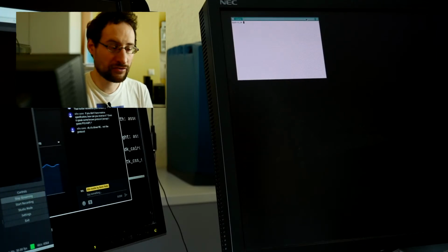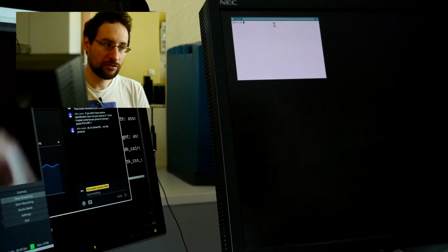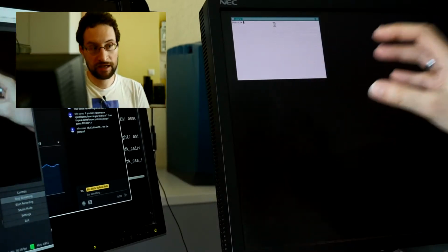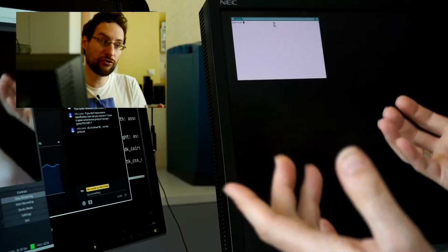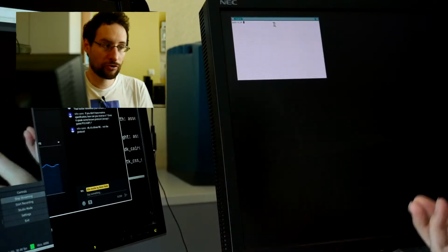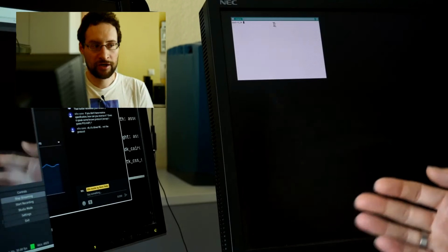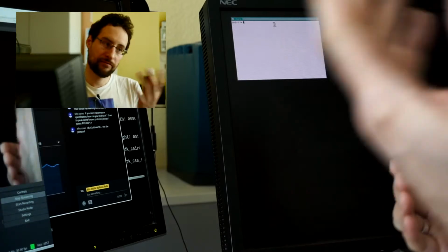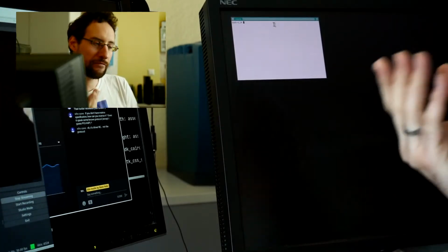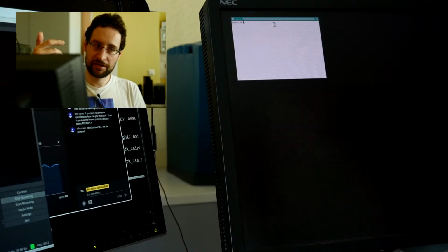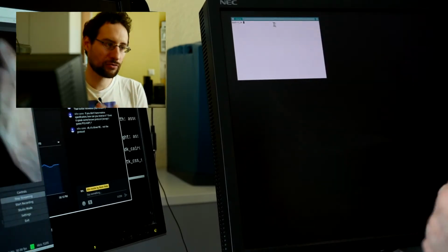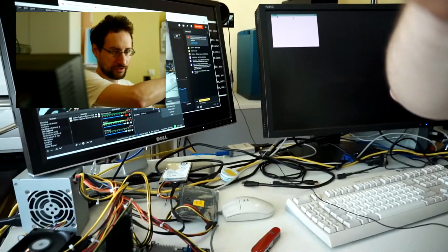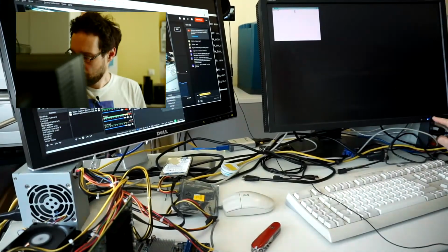So just doing this carefully on some corner, you should already have hundreds if not thousands of register writes in your log. If you don't, then you're tracing the wrong thing. Then you need to look more closely, and analyze what other devices are opened, like in my case /dev/mem versus this device PCI resources and so on. So you're just looking in the wrong place, and you need to look in more detail. So now we have this trace.